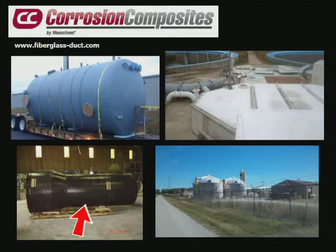That happens to be, the big culprit there is sulfuric acid that's reaching its dew point due to the moisture and the temperature change. And what we've made that with is a high temperature vinyl ester resin. It has a heat distortion temperature of 470 degrees. And it's also filled with carbon. It has a carbon veil, and it has carbon graphite powder throughout it. So that's an unusual piece.